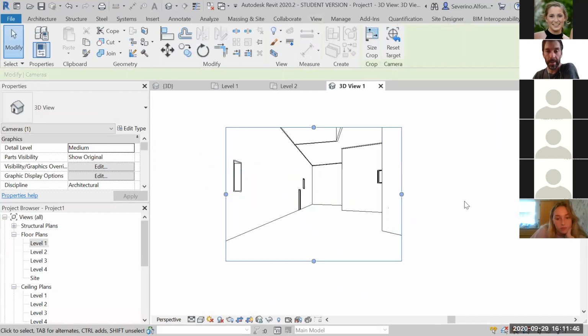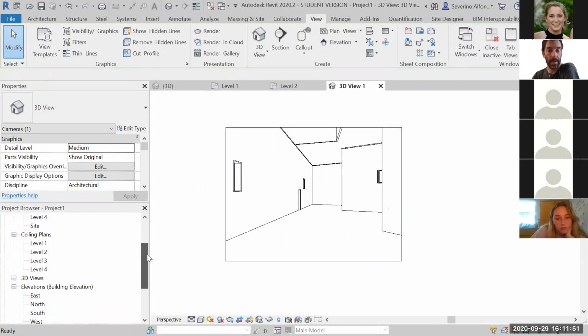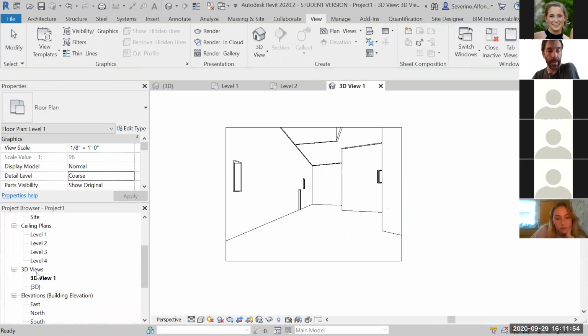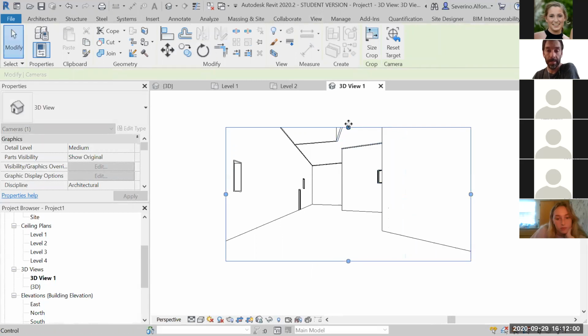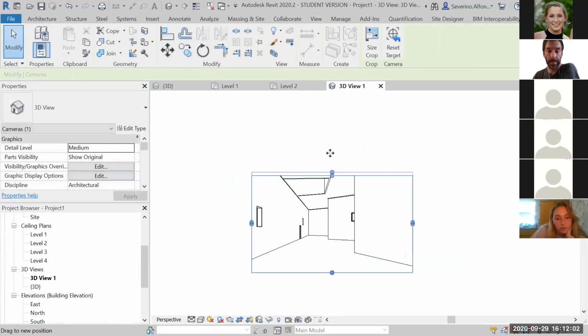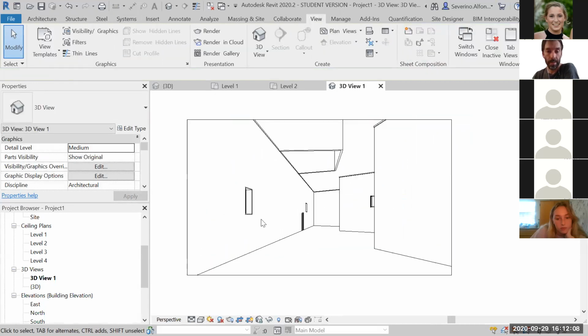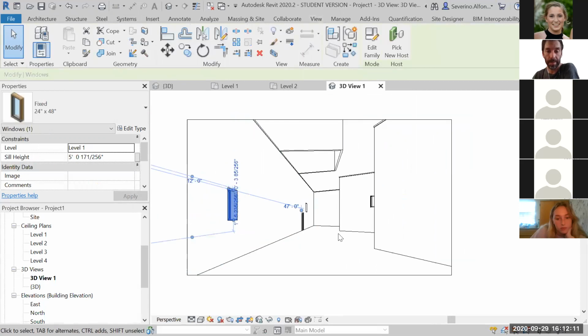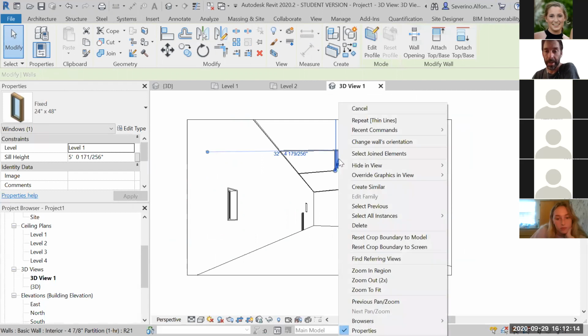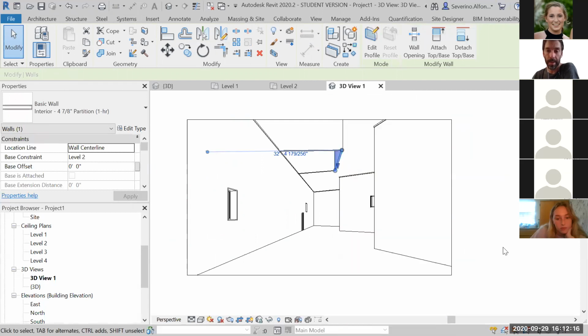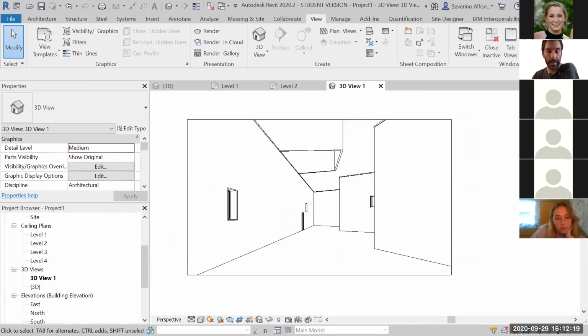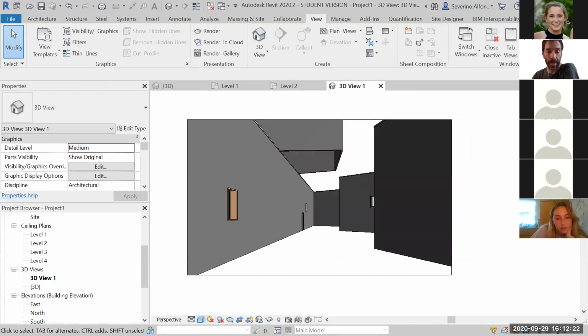Automatically, you're given an interior perspective, which automatically creates a little tab here under the 3D views. And you can modify how much you see, right and left, top and bottom. If you want to move things, you can move them even from the perspective. You can hide things from the perspective. Sometimes it's useful. We'll talk about hiding in a second. And obviously, you can see this in different ways. You can see this as Raytrace already to see how it will look.